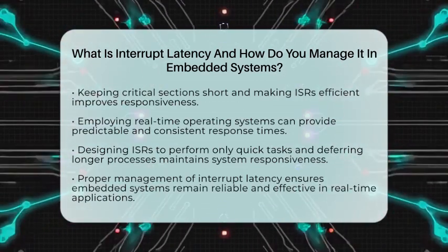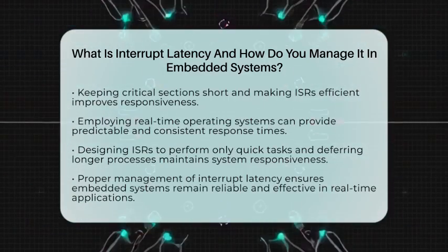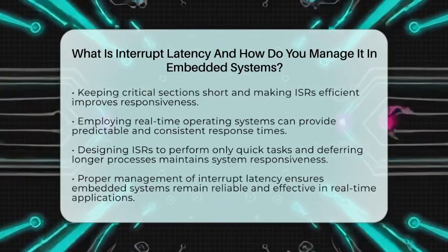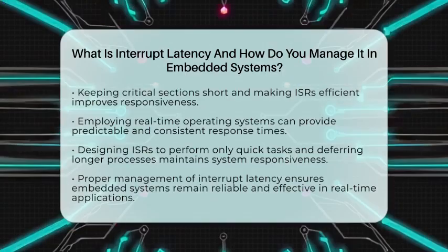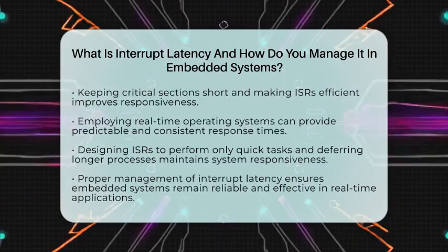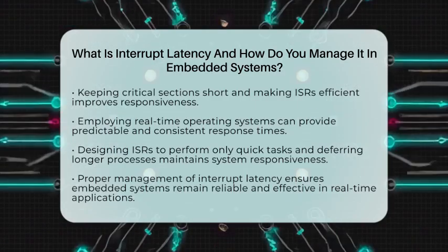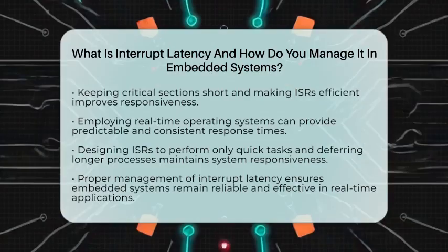timely responses are vital. In summary, interrupt latency measures how fast your embedded system can react to external signals. Managing it involves hardware choices, prioritization, minimizing disabled periods, and using efficient coding practices. When done right, it keeps your system responsive, reliable, and ready to handle real-time challenges.